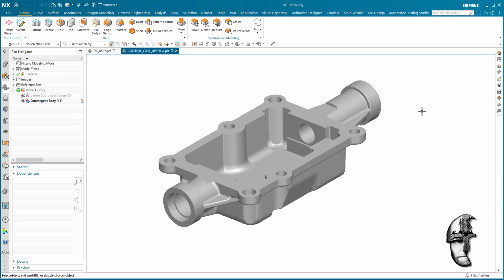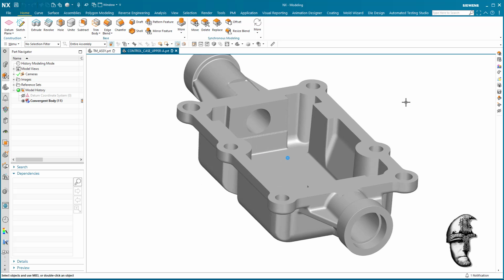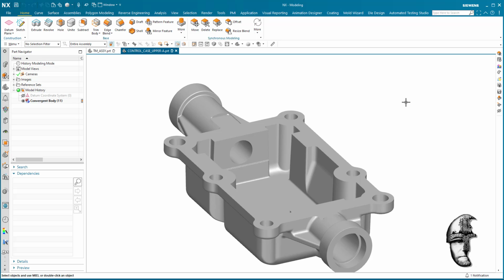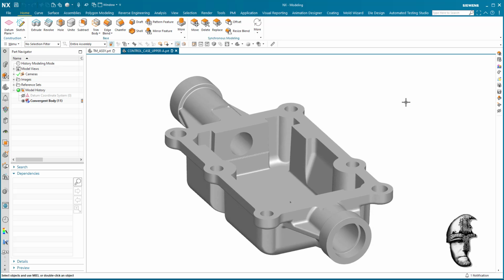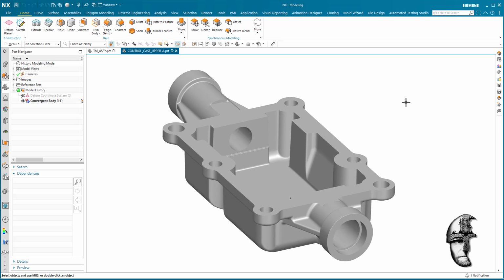Okay, so this is a faceted body, and we are going to need the inside and outside to be kind of separated by face, if you like, because we're going to do a Boolean operation here, and that will require an inside face and an outside face.